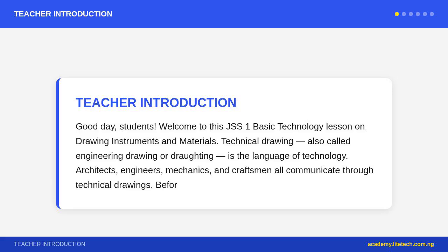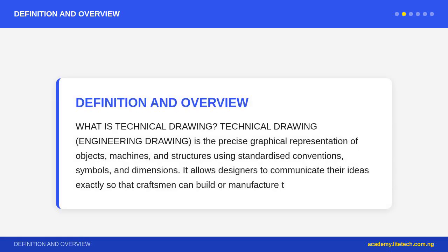The drawing board and T-square. Drawing board: a flat, smooth, rectangular board, usually wood or laminate, to which drawing paper is pinned or taped. Standard sizes correspond to paper sizes, A1, A2, etc. T-square: a T-shaped ruler. The head slides along the left edge of the drawing board, and the blade draws horizontal lines accurately. Always draw from left to right when using the T-square. Together, the T-square ensures all horizontal lines are truly parallel.